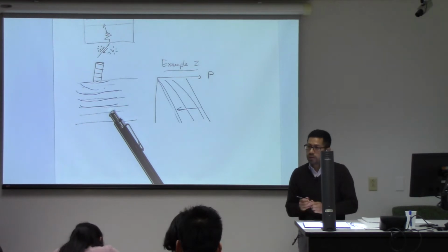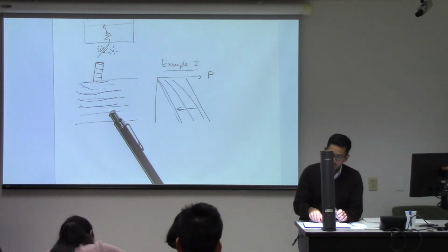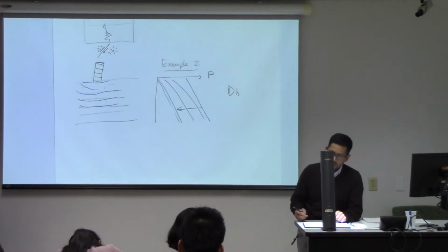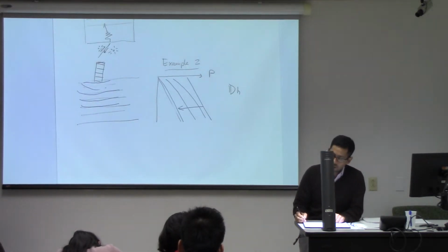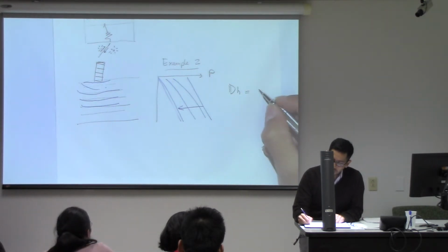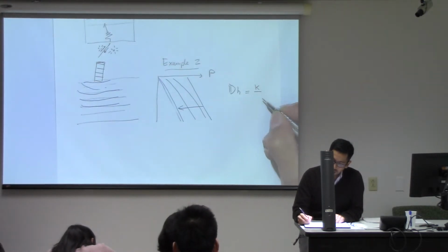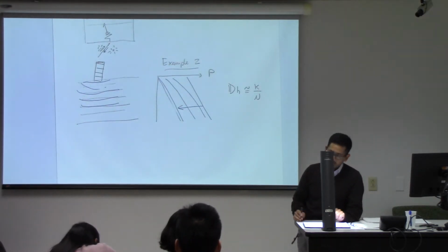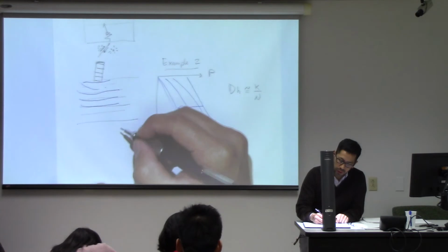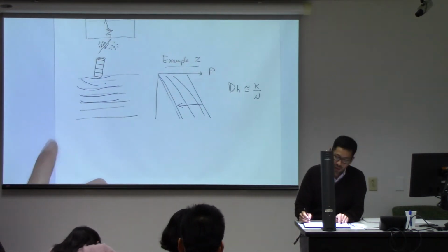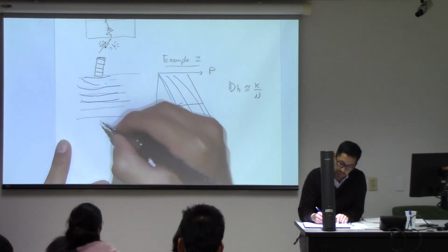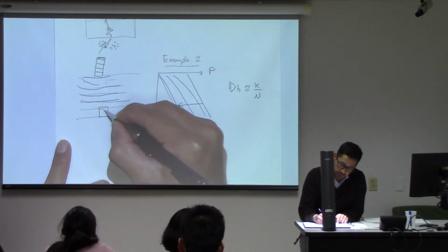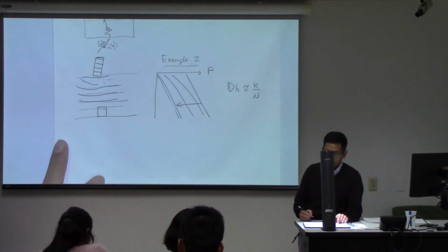And what is that going to depend on? It's going to depend on the diffusivity parameter. And that diffusivity parameter, if you remember, is K divided by the viscosity. In this particular condition, we're going to assume that the strain is just in one dimension, something that we have called one-dimensional strain.